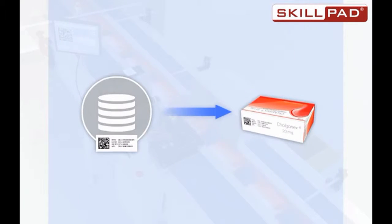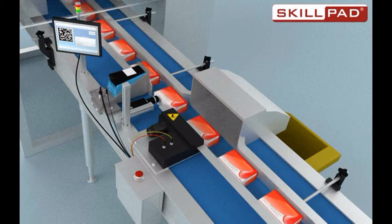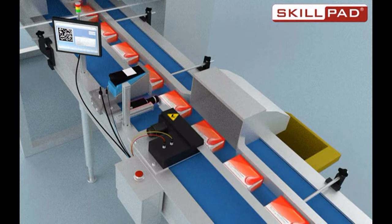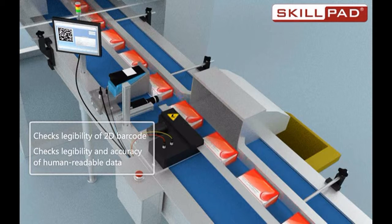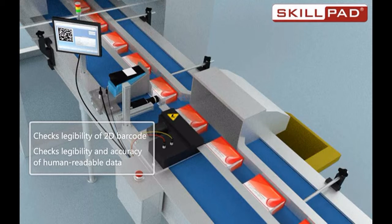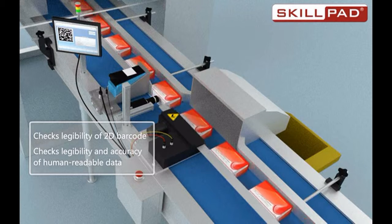It is at this point that the serial numbers make the critical transition from digital state to physical state. When the data is printed on the item or label, the now physical serial number must be checked by the scanner. The printed items pass through a scanning zone, and scanning cameras read the printed data. The data is checked for legibility of the machine-readable elements. That is the 2D barcode. Some scanners also check the human-readable element and the overall printed data accuracy.